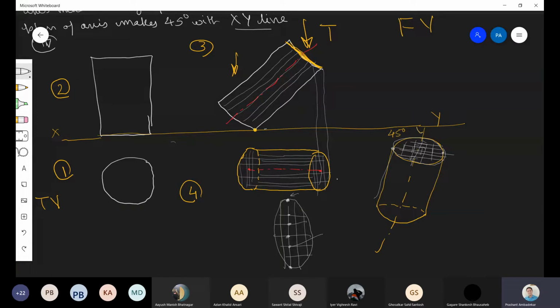And then this is which view? Front view. For drawing the front view, you will see this object from here, and we will write here F. See, this is important to write. I am writing here F and I am writing here T. So you also start writing it when you are drawing it. Whenever you are drawing it, write T, write F. Now when you draw this,